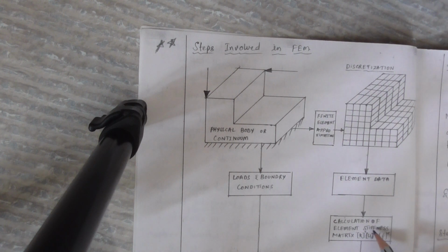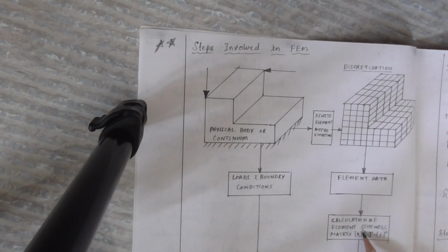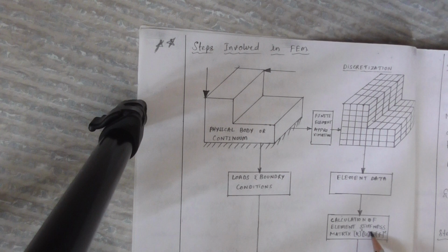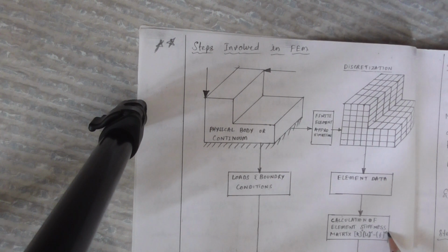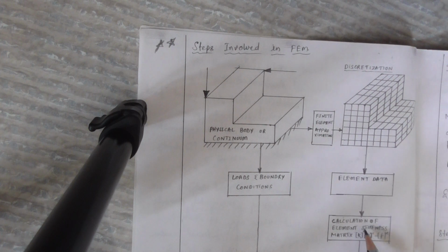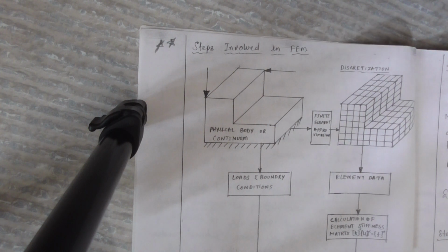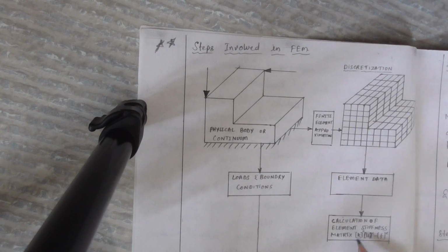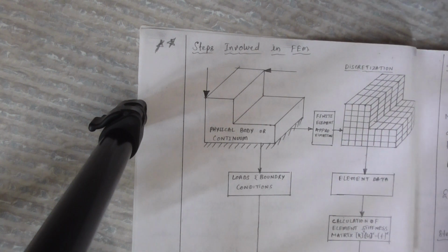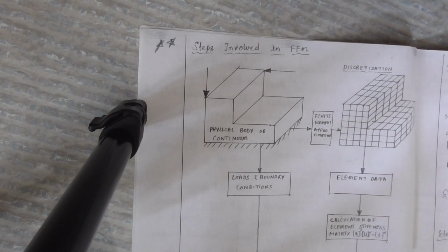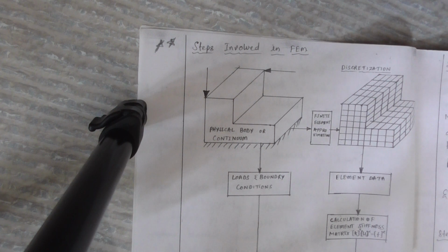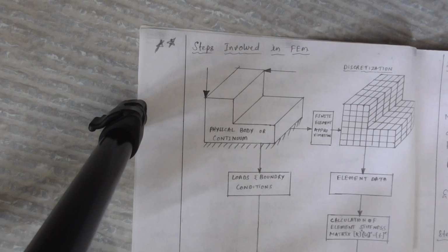Next, after deriving the element stiffness matrix for one element, how many elements are there? We assemble the combination of element stiffness matrices. Here I wrote K superscript e, U superscript e, and F superscript e, where small e indicates that you are deriving the stiffness matrix for one element. Then in the next step we assemble all these element stiffness matrices. How many elements did we divide into? N number of elements, 10 elements, 20 elements, like that. That's why we write the global stiffness matrix, or a combination of element properties: Kg, the global stiffness matrix, into Ug equal to Fg.